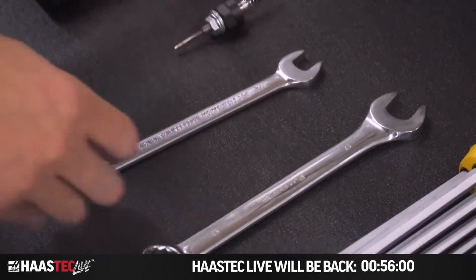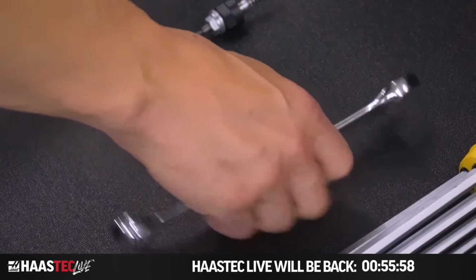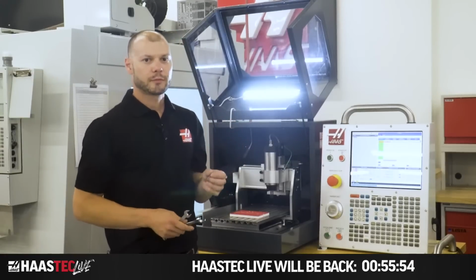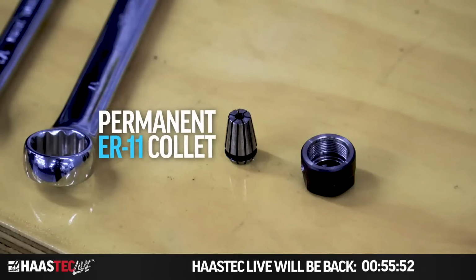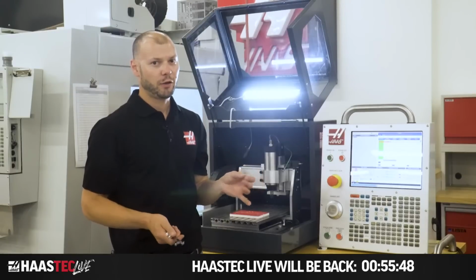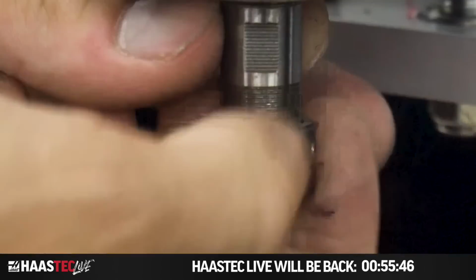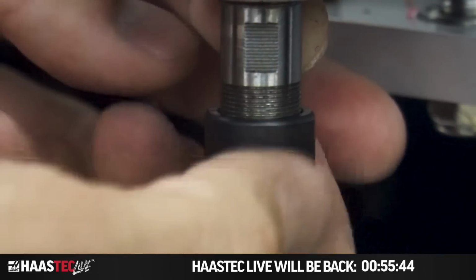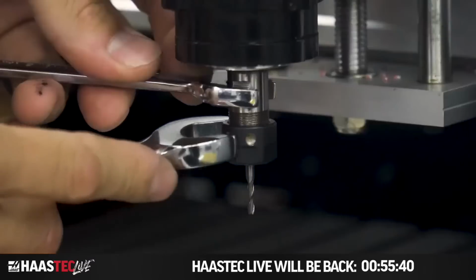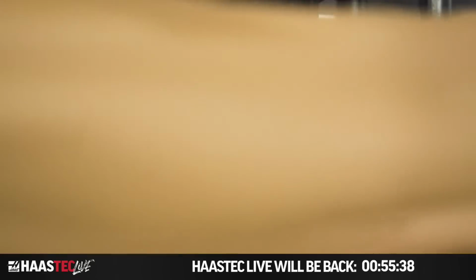So, I have my 1/8 inch 3-flute end mill, and I'll tighten this in the spindle. I should mention the spindle has a permanent female ER11 collet interface for the spindle nose, so you'll need a set of ER11 collets for each machine. Now, I'll tighten my tool in the spindle. It's a small tool, so don't over tighten it.